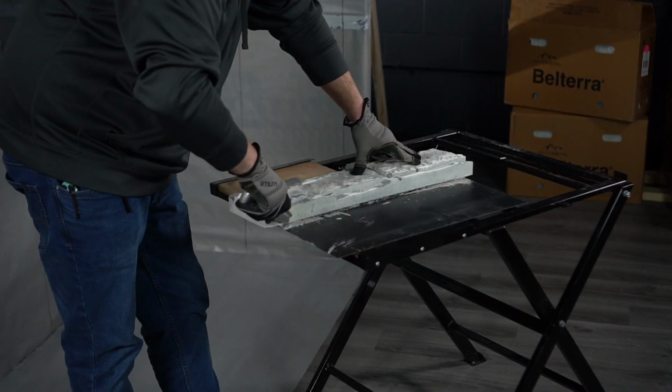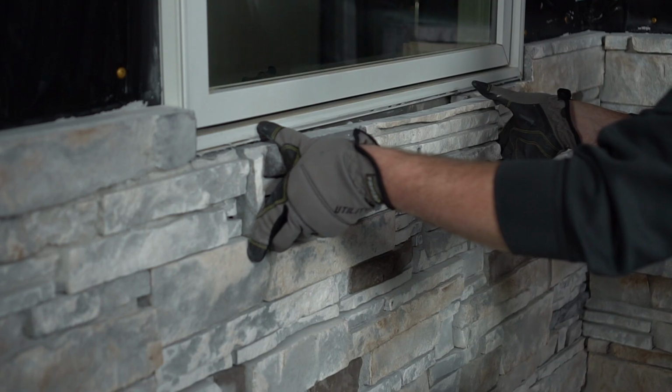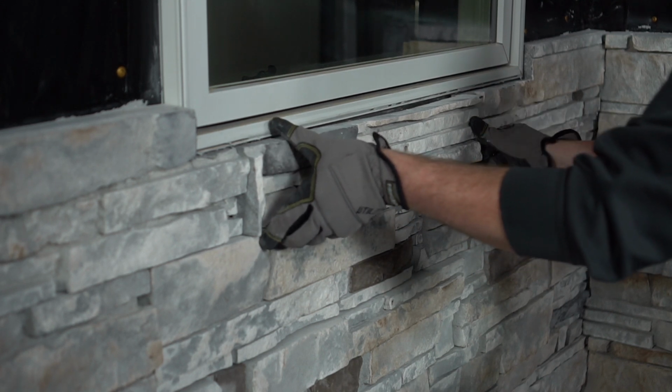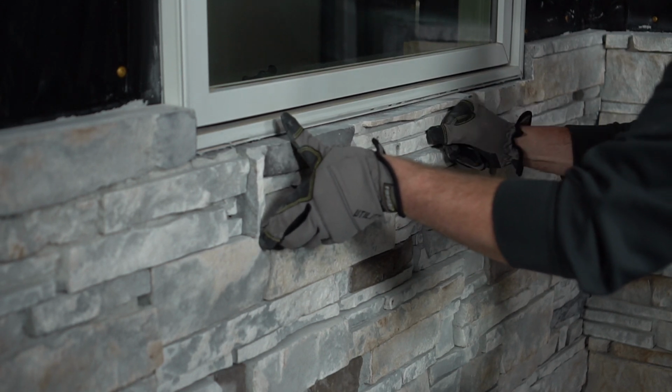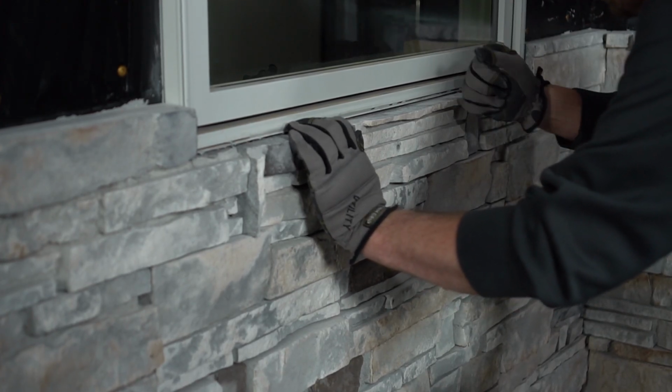Trim flashing off the panel that will mount directly beneath the opening. Cut drip cap so it fits over the modified panel. Cut panel lengthwise so there is just enough room for panel to fit into the space with room for backer rod. Dry fit all parts, leaving a 3/16 inch gap between panel and bottom of the window.